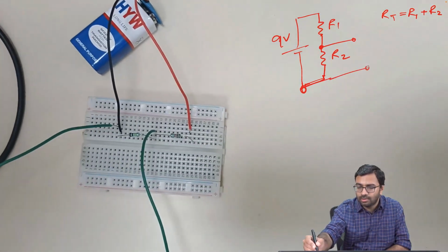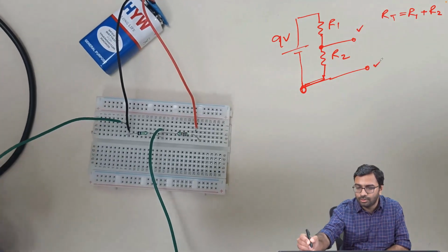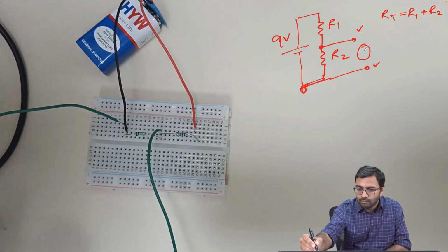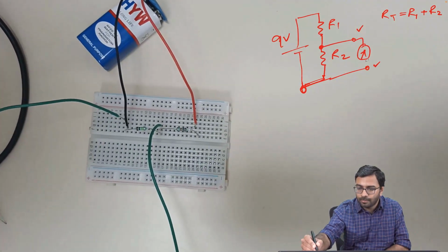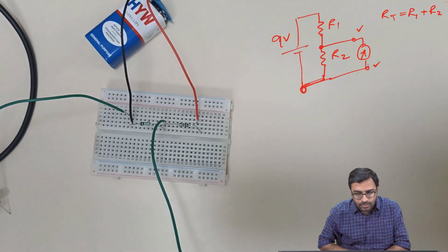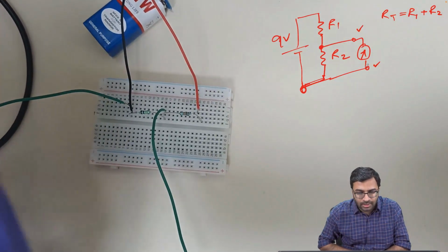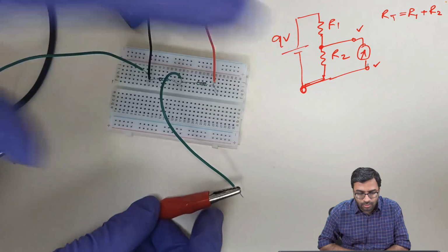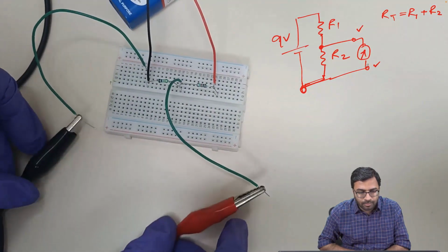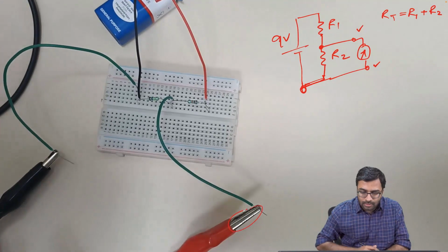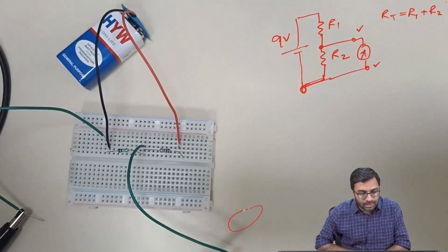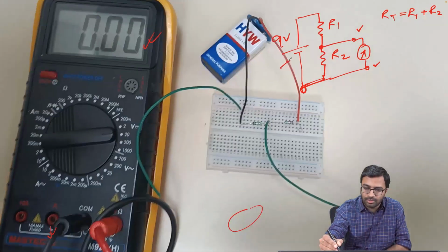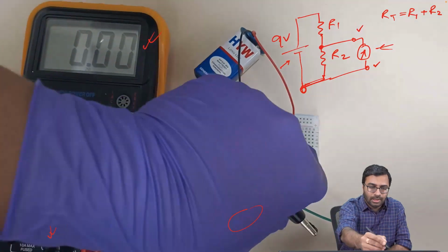So you have now two wires, 1 and 2. Both these wires will be now connected with a multimeter. So now we are connecting the wires with two probes of a multimeter. These are the crocodile clips, and we are connecting the circuit with power source and with multimeter. This is your power source, this is your multimeter. So this is the multimeter display.